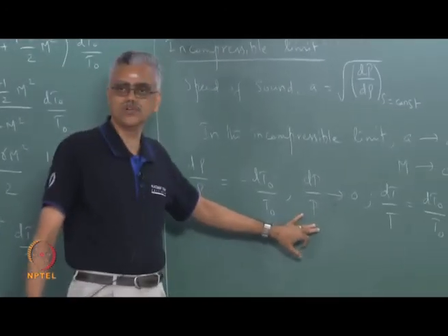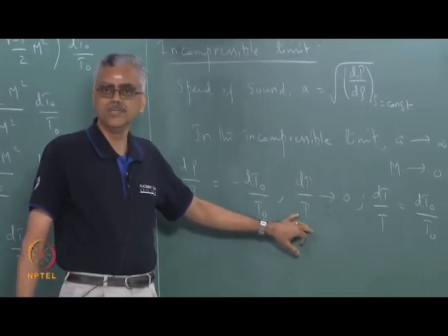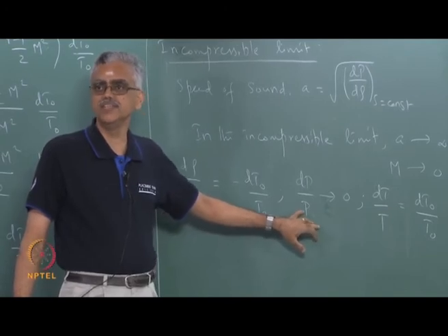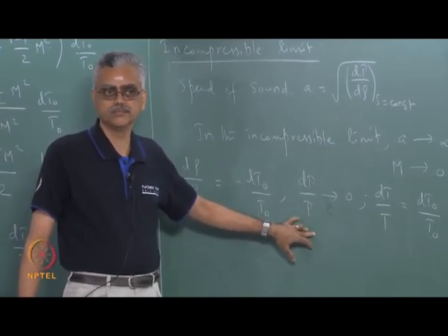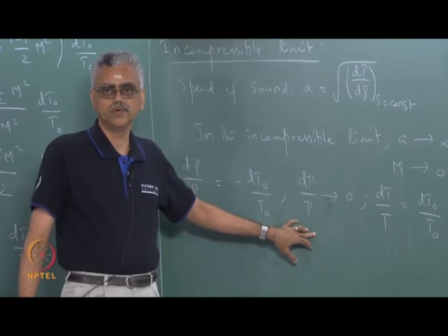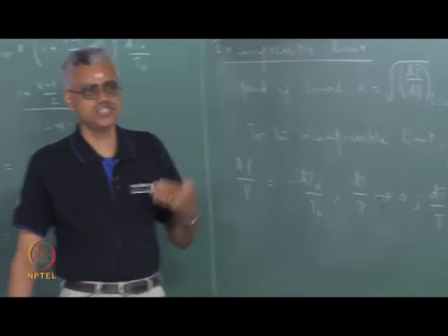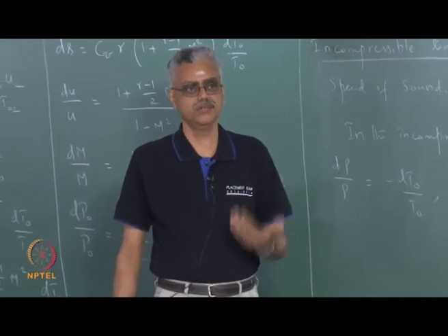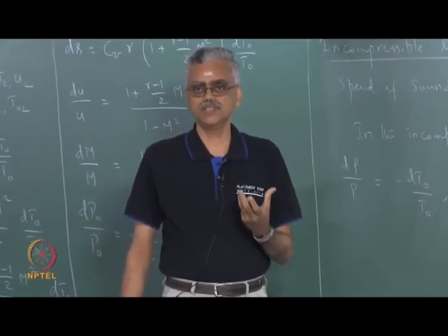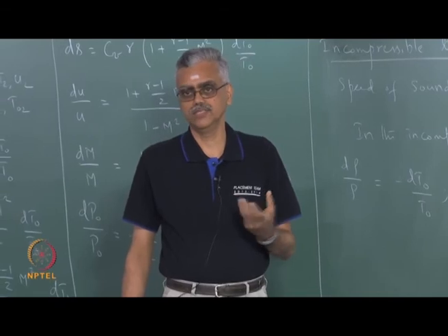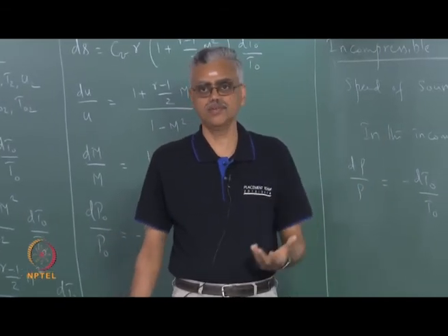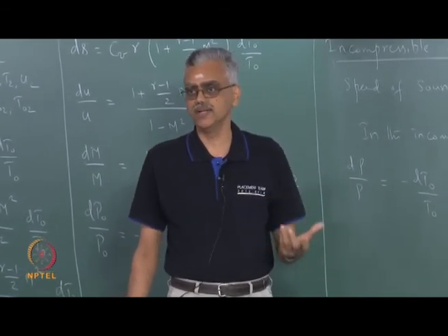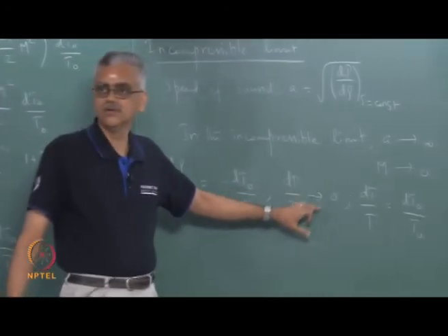The flow behaves like an incompressible fluid in the aviation gas turbine combustor. Okay. So this actually can be used as a check for incompressibility. If I add heat and I do not notice change in pressure, that means compressibility effects are negligible, right. So you have huge furnaces where you are adding a lot of heat, but compressibility effects are negligible. This is the reason for that.